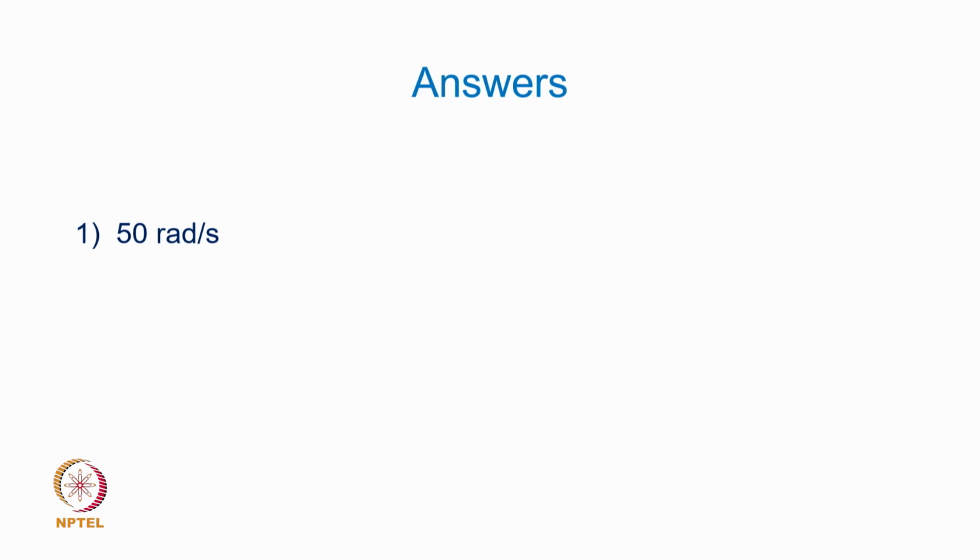So, a simple straightforward question. What we learn from this particular example is that in a multi degree of freedom system, even if the system has many natural frequencies based on, of course, the number of degrees of freedom, if the system is subjected to a harmonic force excitation at a particular frequency, the response of the entire system will be at the forcing frequency.